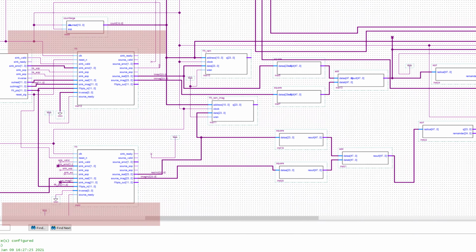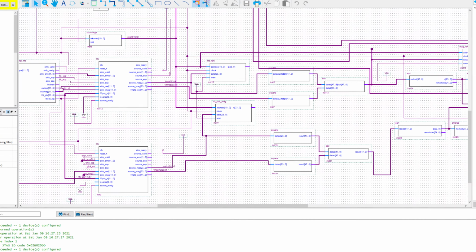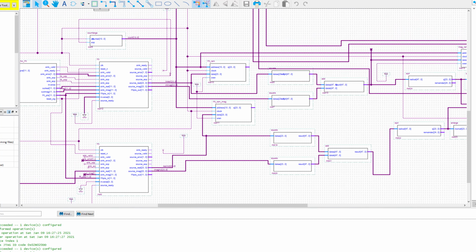Now, those signals are going to these blocks here, so it's basically a square and then add. So that's just an easy way to go from rectangular components to the magnitude, because Pythagoras' theorem, the square root of real squared plus imaginary squared, gives you the magnitude.